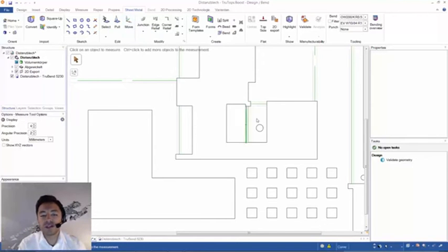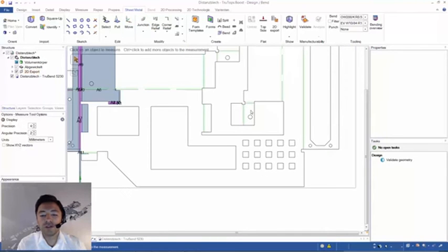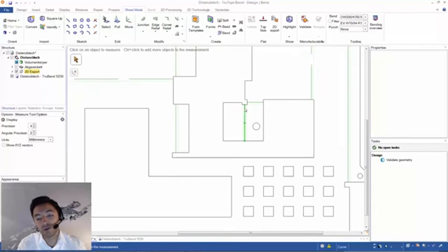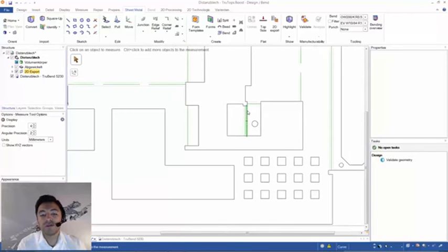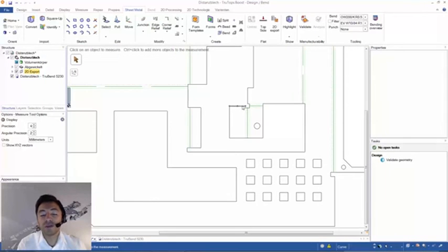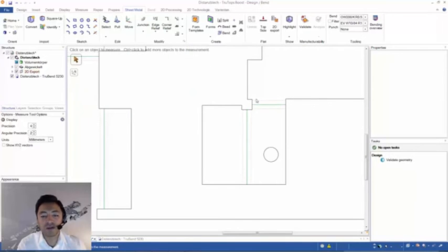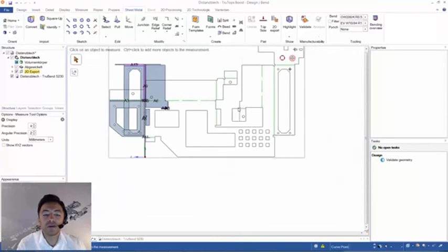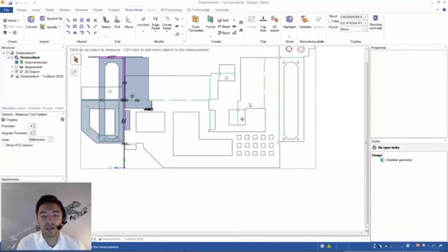So you can still adjust, for example, that bend relief. And what you have to be careful about, of course, it will be lasered, but the 3D model won't be updated. So if you want to create a special laser cutting program without modifying your 3D model, it's possible. But you have to be careful that it won't rebuild your 3D model, but vice versa, you can adjust your 2D export without editing your 3D model.